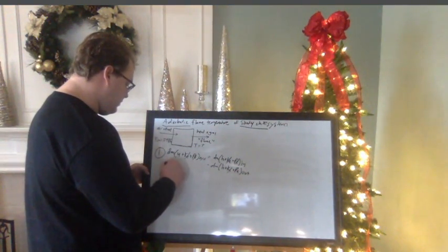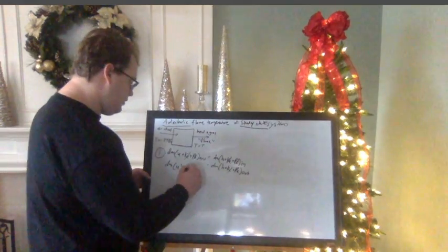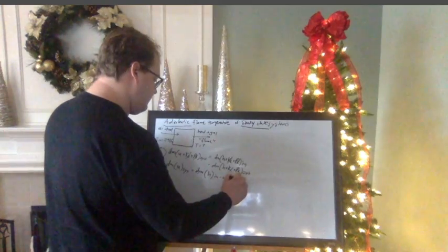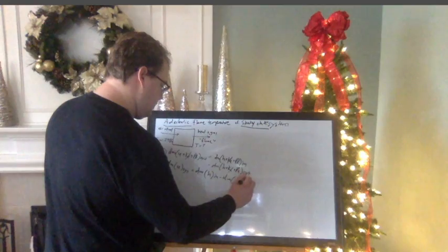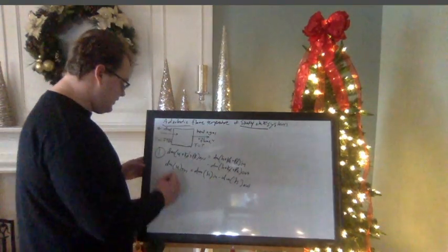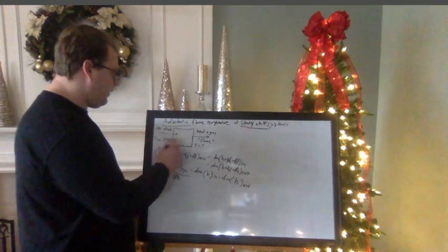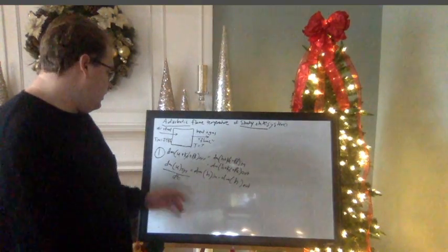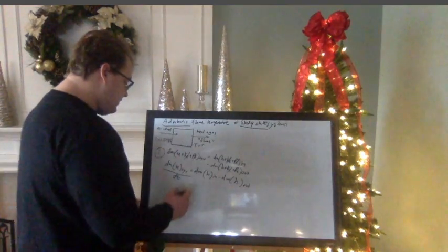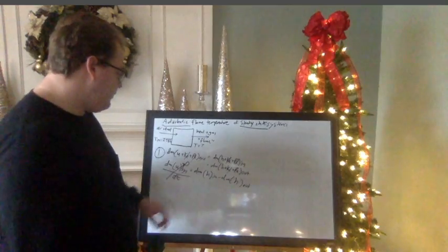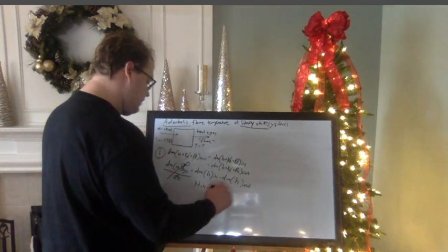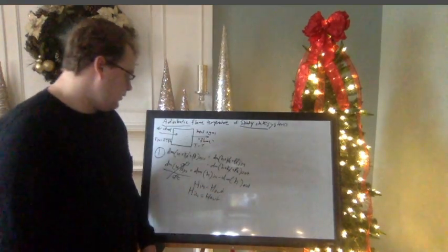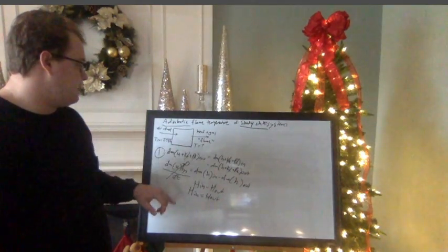So we're left with the change in mass, the internal energy of our system, is equal to the change in mass, H in minus H out. Oops. We also know that this is with respect to a certain amount of time of our air and our fuel going in and then exiting, so it's with respect to time. And we also know that the internal energy of our system is not going to change, so we can set this all equal to 0, and we're left with H in minus H out. Or we can say enthalpy coming in is going to be equal to enthalpy coming out. So in the most basic form, I've simplified our energy balance for our system, knowing that it is adiabatic and steady state.